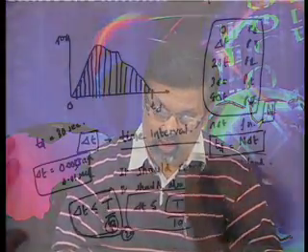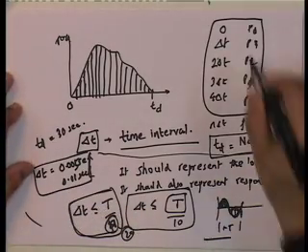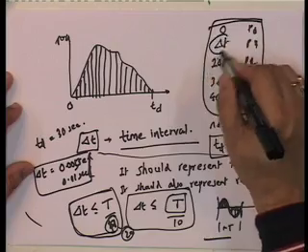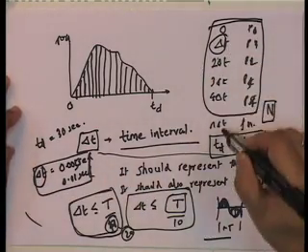We will show you when we go to the lab that there are some data acquisition systems that can do it at 1000 samples per second. In other words, delta t is measurable at 0.001. So, let me be very clear. What we are doing here is looking at, for the numerical analysis, this delta t may be different from this delta t, because this is more digitization.